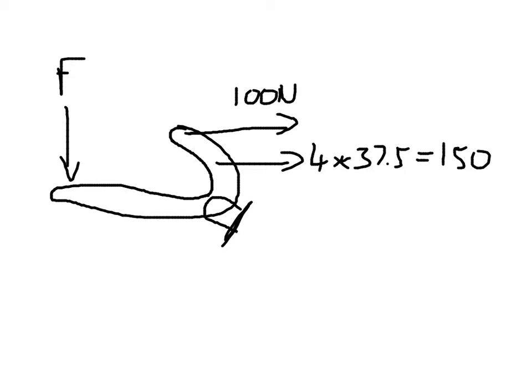But we've also got some other forces, some reaction forces, which I'll just draw in green because these are the new bits for today. Because it's a pin joint, we're going to have a force in the y direction, and we're going to have a force in the x direction. And you could label them AY and AX. We're calling them A because this is point A, labelled in the original diagram. So that's the new bit for today, thinking about reaction forces and adding them to the diagram.